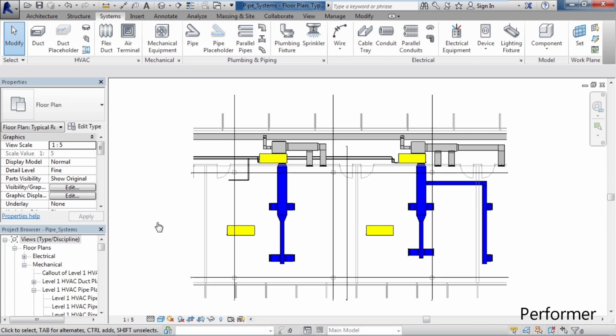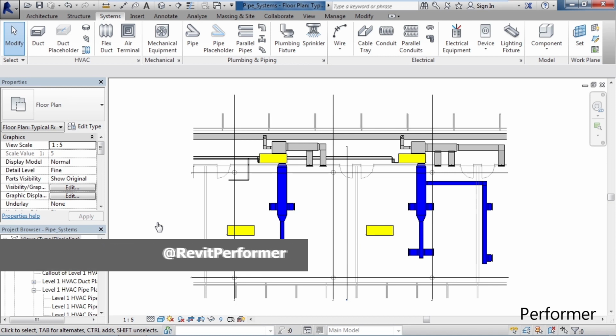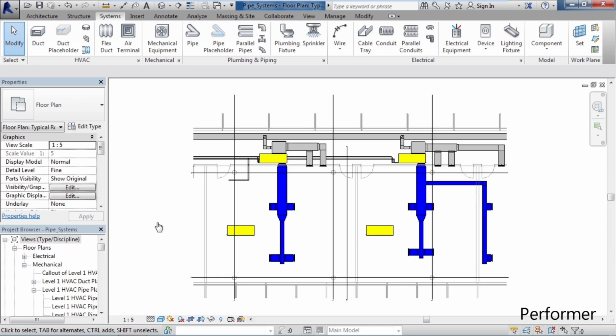In this lesson, we'll cover pipe systems. Before you start to build your layout of different pipes and components of your pipes, whether that be fittings or accessories, you need to define a pipe system. The pipe system is technically the glue that holds everything together. It's also needed for analysis. Basically, it'll analyze everything in that system or what belongs to that system. So to create a system, I need to first create at least one piece of equipment or a mechanical element.